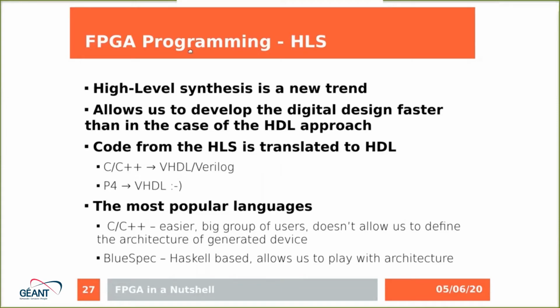Now just a few words about high-level synthesis. High-level synthesis is a new trend because it allows you to develop the digital design faster than in the case of the HDL approach, and this is caused by the higher level of abstraction, because in high-level synthesis you are not working on a clock level, you are just expressing the algorithm you want to implement inside the FPGA.